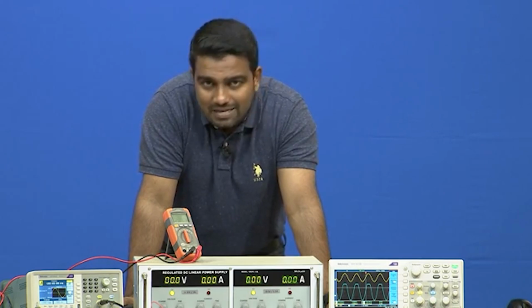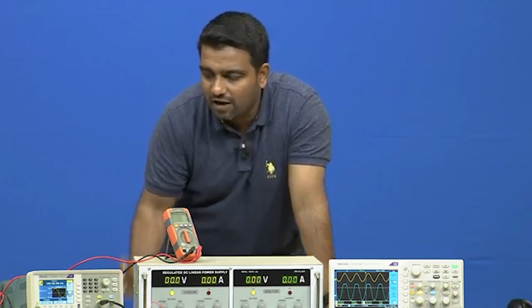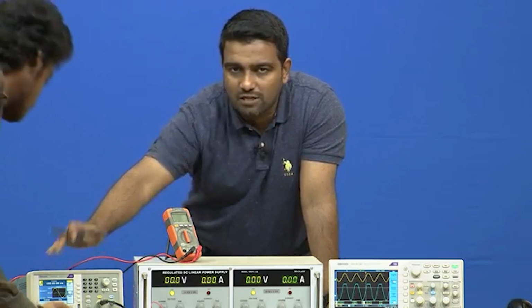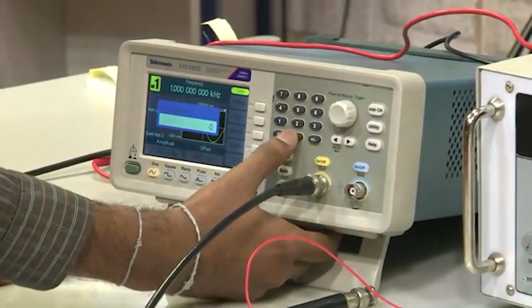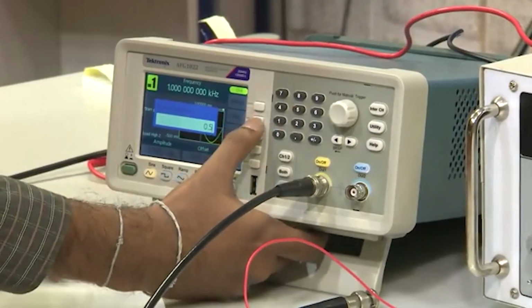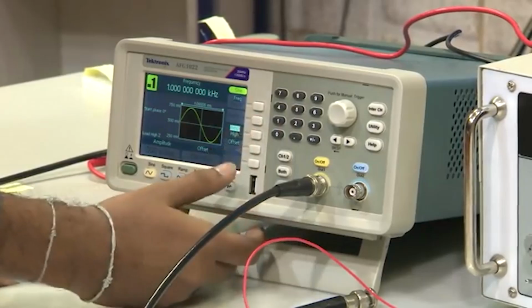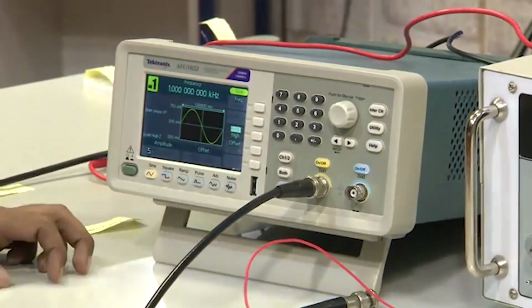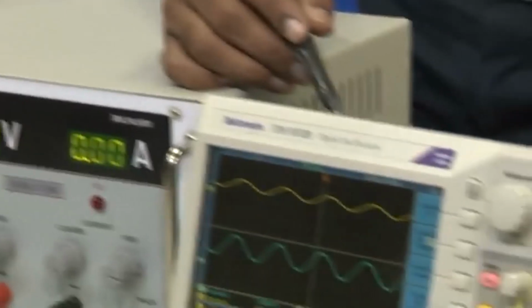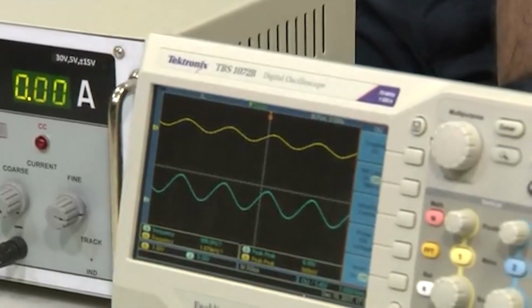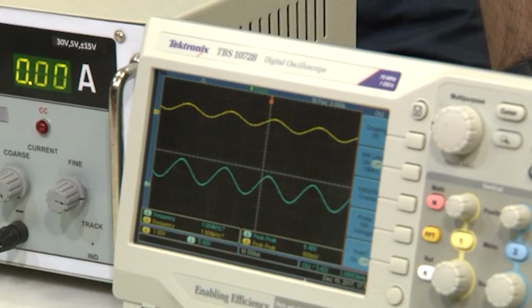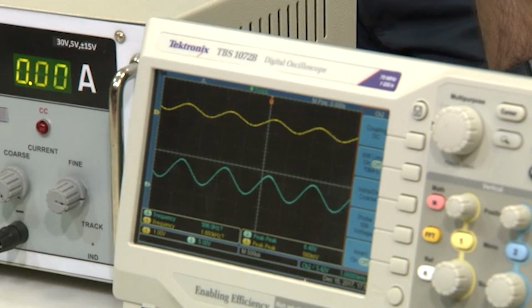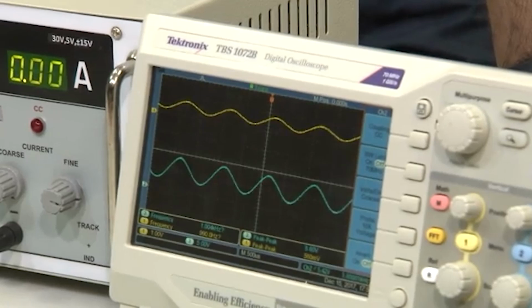But what if we decrease it? Let us quickly decrease the voltage here in the input. Let us say we are applying about 0.5 volts peak to peak, which will give us output which we can see here in the oscilloscope, right. It has amplified about 11 times. So, 11 times 0.5 would be around 5.5. That is what we can see, about 6 point something volts actual.